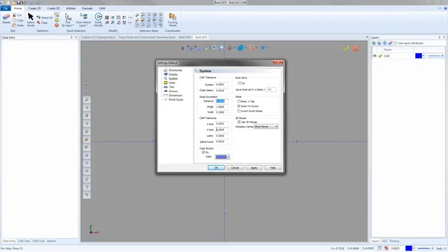So what this enter equals tab button does is it, just by checking it on, it converts when you hit enter to act like you hit tab. So instead of it creating the geometry, it's just going to advance you down one box. That one's a really good one. I've seen guys, some people, their fingers automatically hit the enter key when they type in numbers.